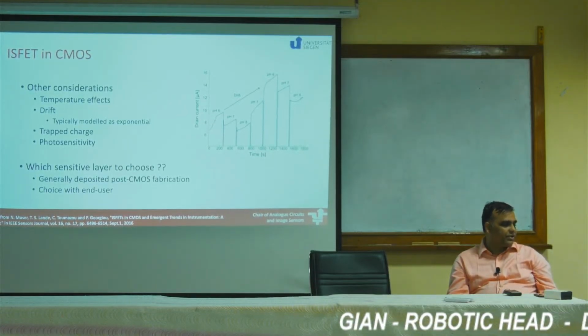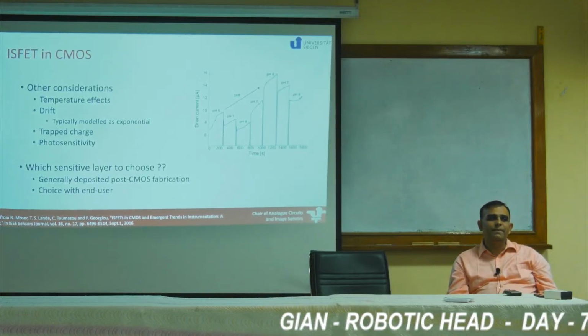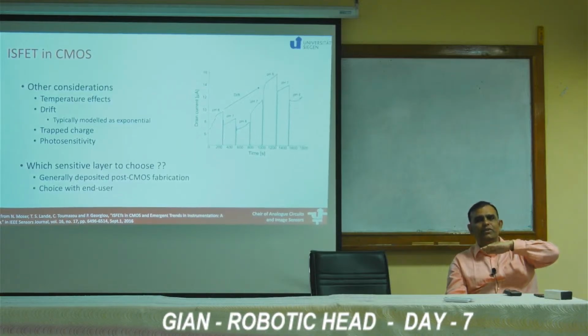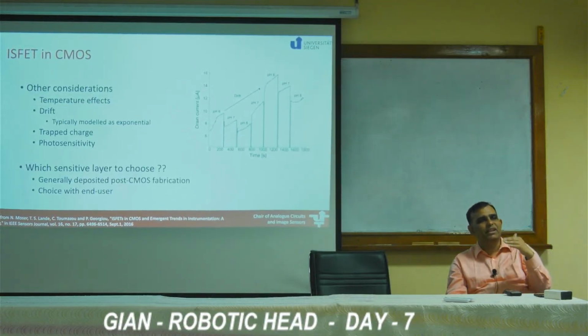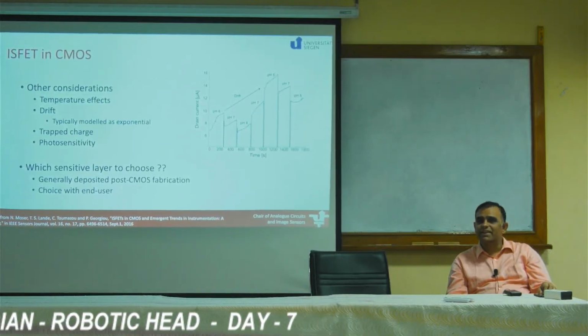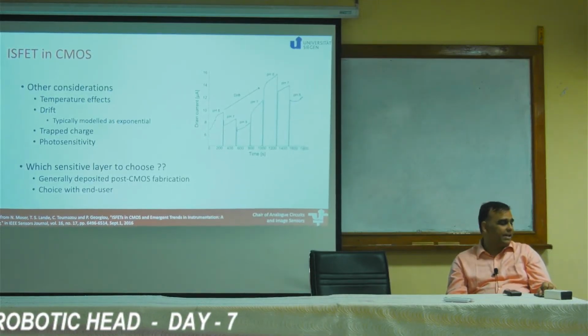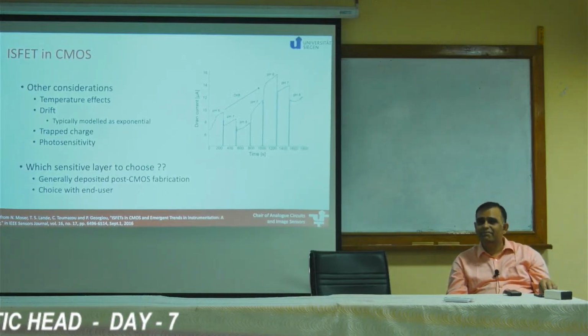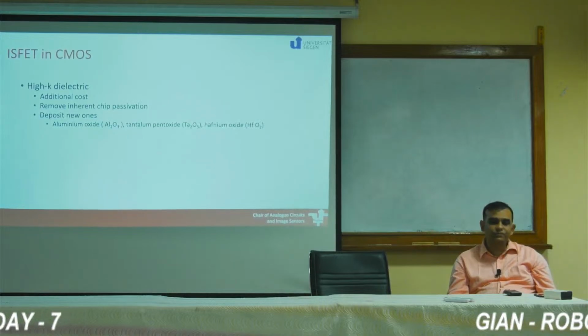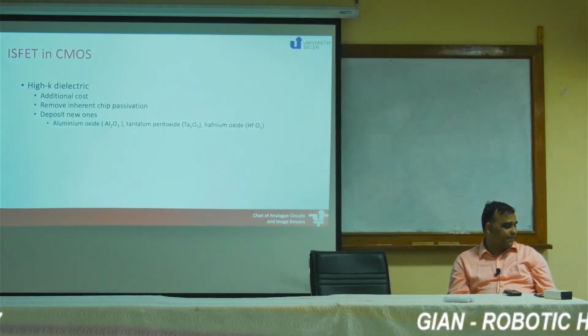So, some solutions to these problems require the top dielectric which we had. Initially, we use the classic passivation layer which is available in the silicon process, that of silicon oxide and silicon nitride. A solution might be to use a better material than that. Ideally speaking, a high-K dielectric would be nice.